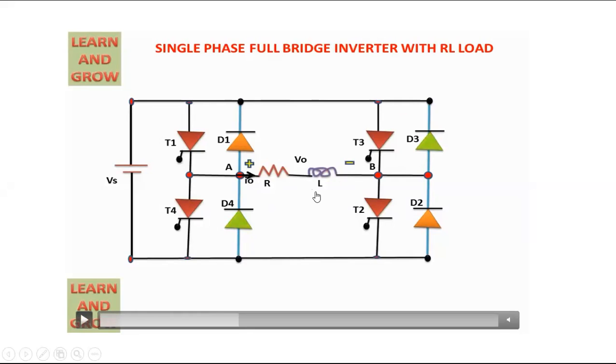When inductor de-energizes, the de-energizing current flows from L plus. This will be L plus now. From L plus, you can see where it will flow: D3, and from D3 to the source. So you can ask, sir, how does the current flow from inductor to source? Because now when inductor is completely energized, the voltage across inductor is greater than the source voltage. So that's why the current flows from high voltage level to low voltage.